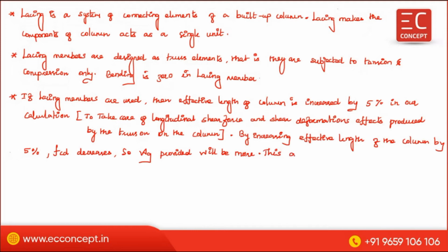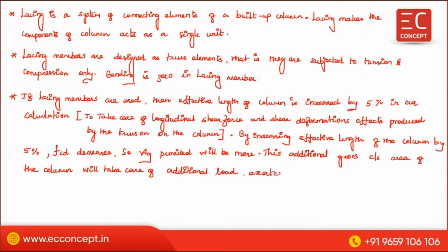This additional gross cross sectional area of the column will take care of the additional load exerted by the lacing system on the column.